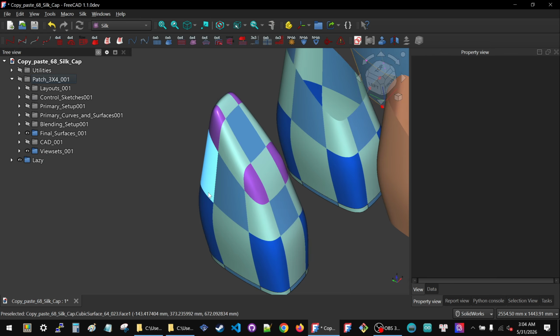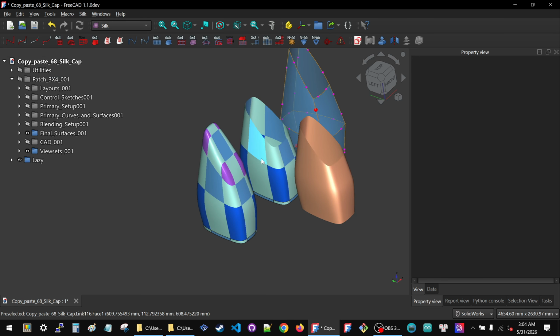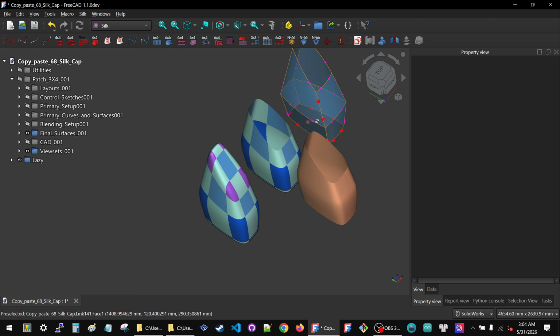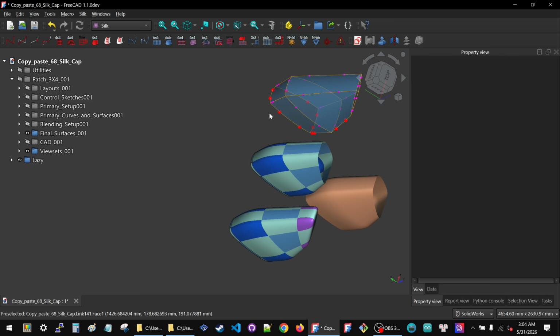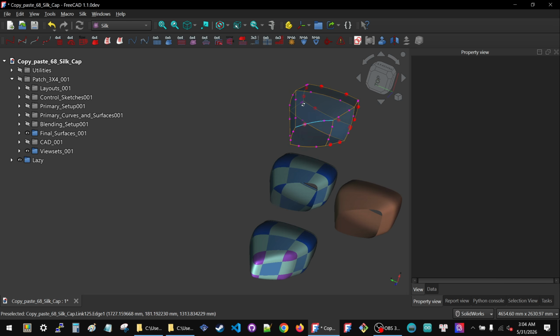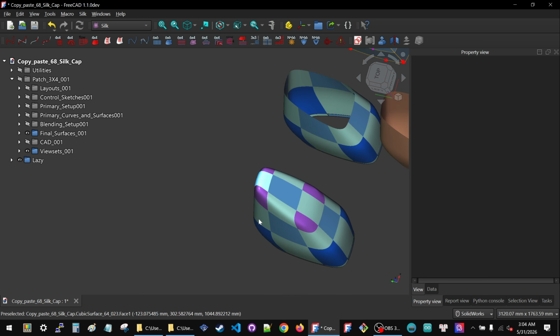But there is one thing I didn't do last time, which we have to do now, and that is we need to look at what happens with the cut points. Because these faces used to be independent. Like the two faces on this side had cut points that followed in this direction, but they were not doing anything to the cut points on this side. Now the cut points that go across this top surface here have to match, at least for the time being.